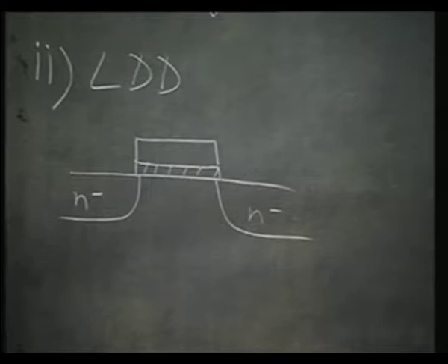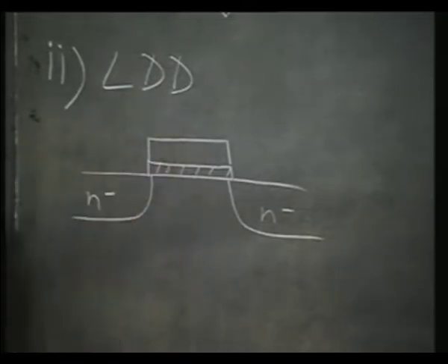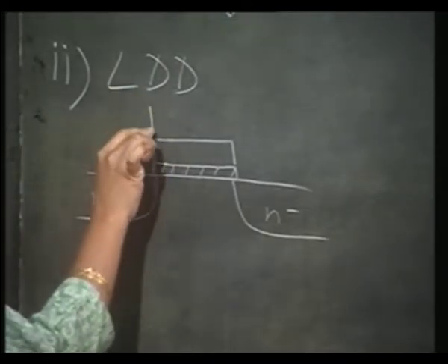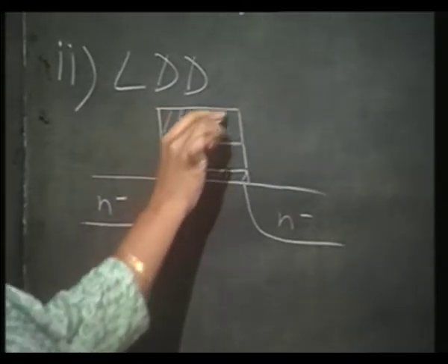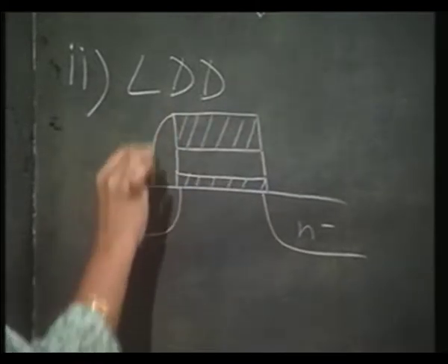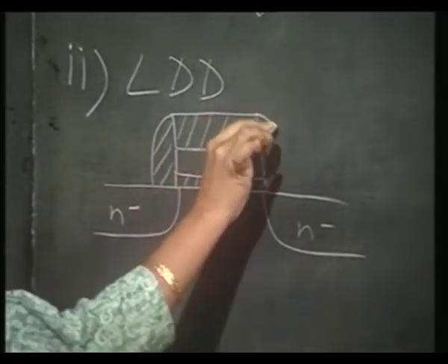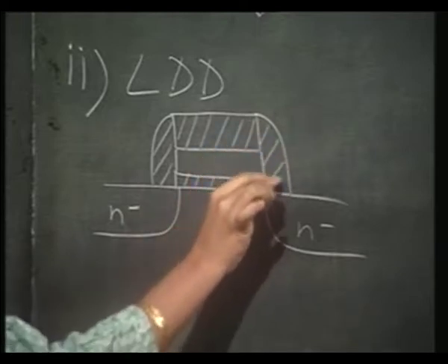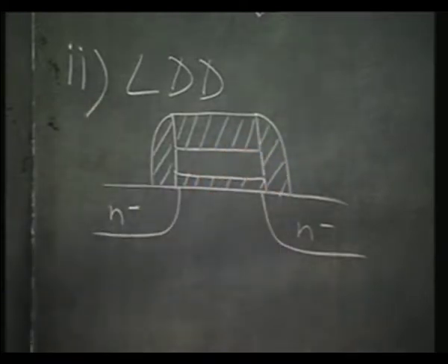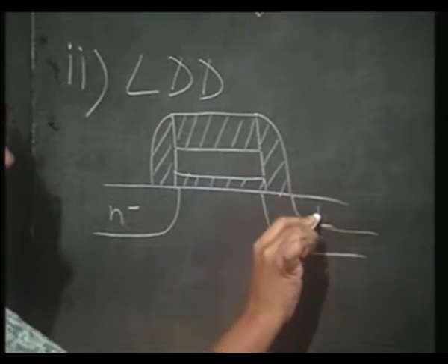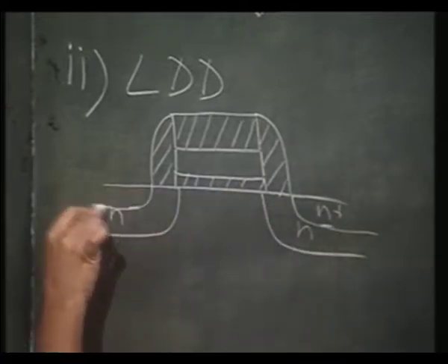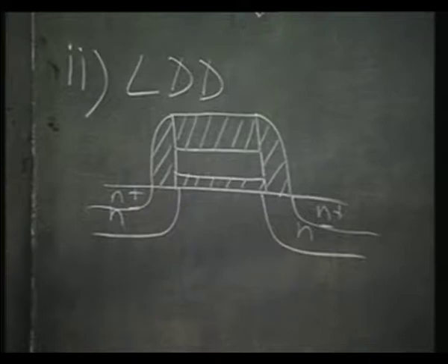And then we deposited a layer of oxide and patterned that oxide, and a second layer of oxide, so that finally what we had was a structure like this, right. Sidewall spacer for the LDD structure. So, the next implantation gave us this, the LDD, lightly doped drain structure.